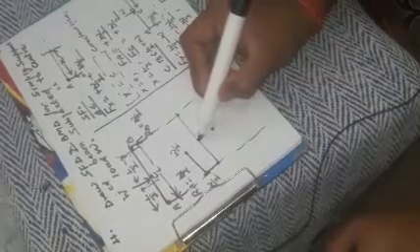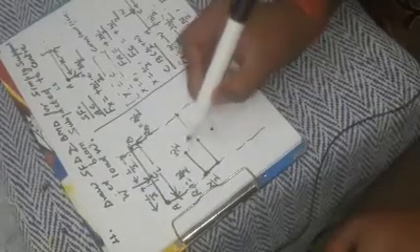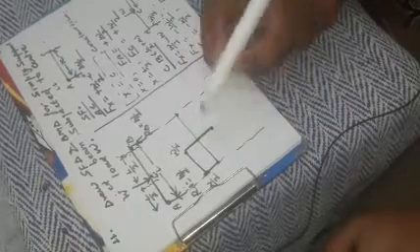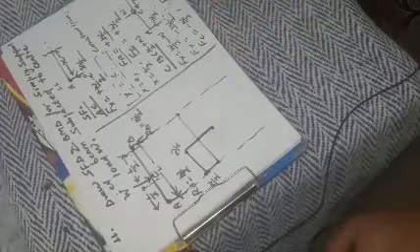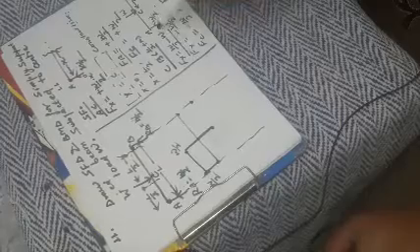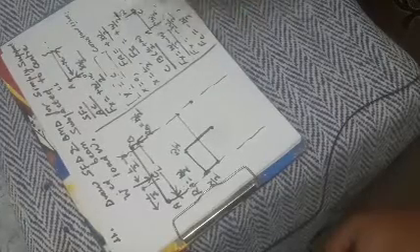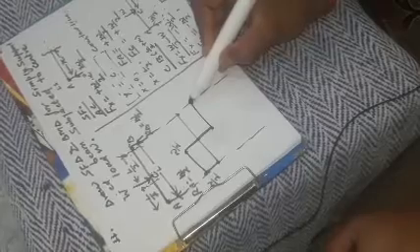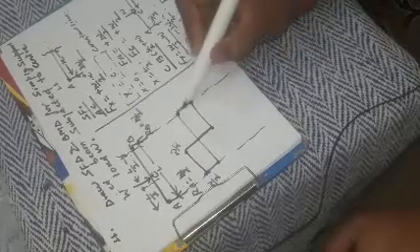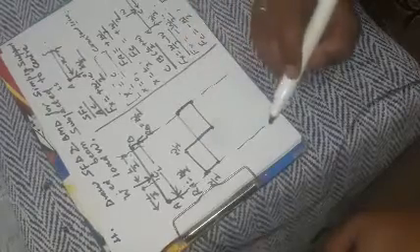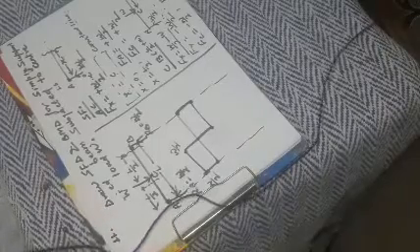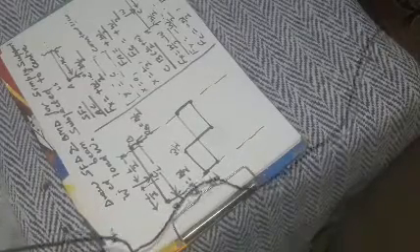At this point, at point C, here it is in upward direction, downward direction, within we will make a line, right? And for B, it is minus W by 2 again, and the equation is independent of X. Here will also be a constant line, and at the end of the section, shear force is always 0. So we will make a closed curve. This is the required shear force diagram for a simply supported beam subjected to center load. Right?